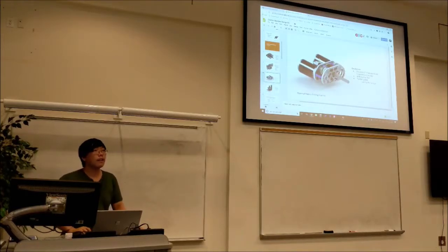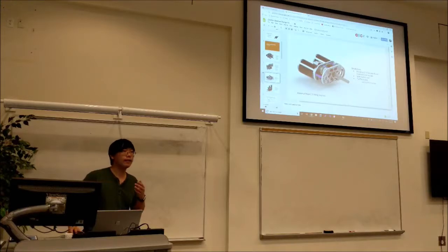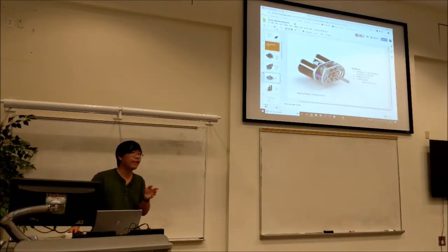So it's always touching both at the same time? Yeah, it touches both sets of gear ratios at the same time, but the output gear is actually on a bearing. So they'll freely rotate until the dog is pushed into the teeth on the gear. You can kind of see it on the output there.